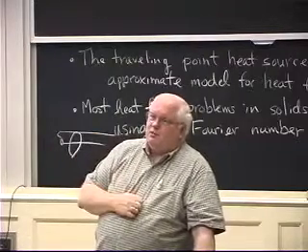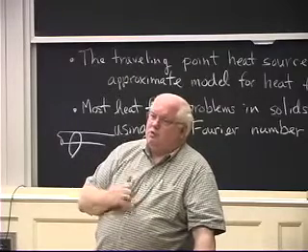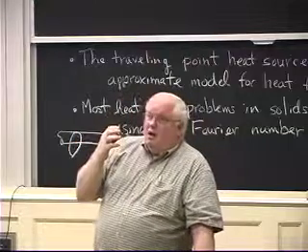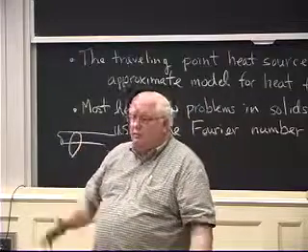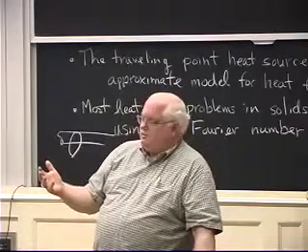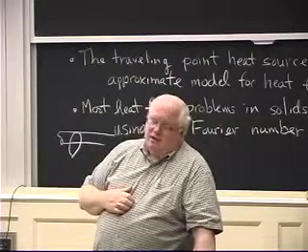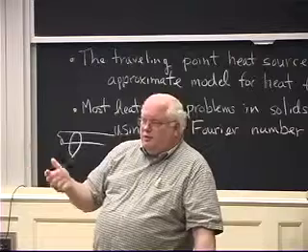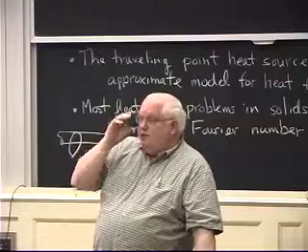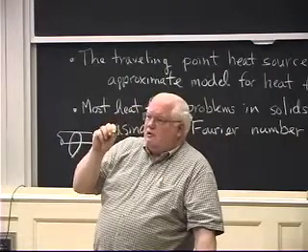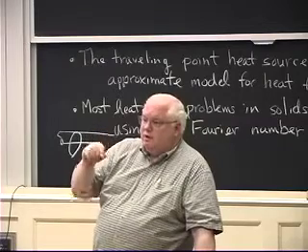I wrote a paper about 20 years ago, a white paper, which wasn't published. Actually, maybe it was published later with Professor Masaguchi, about 10 years ago, on what you should use in space. Now, you don't want to use an electron beam that's 100 kilovolts because you have the problem of insulating the welder from 100 kilovolts plus the X-rays. Right. You could use 40 kilovolts, but you still have the possibility of electrocuting your astronaut. It would be much easier. You can actually make something like a gas tungsten arc heat source out of a 10 kilovolt electron beam. Now, we would never do that on Earth